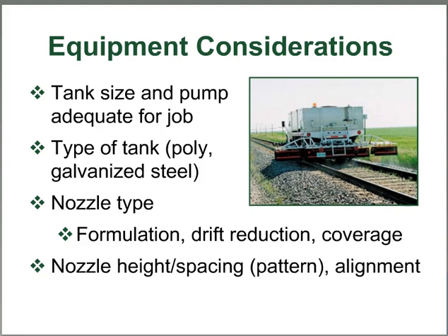Are the nozzles correctly set at the proper height and spacing to give an even pattern? Are they aligned to spray past each other and not spray into each other? Does your pressure gauge accurately measure pressure? Is the pressure set in an appropriate range for the nozzle to perform? These are all extremely important questions that you need to address before each pesticide application.